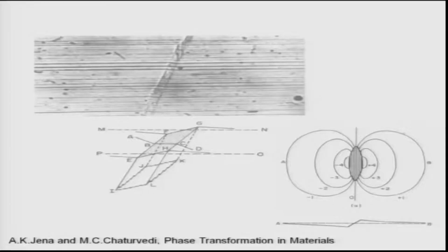You can see there is a distorted region along these lines. Let me just show it. Okay. Anyway, this is the distorted plane, as you see here, along these directions. Now, one can look at the scratch. The scratches were moving on the plane of the parent phase austenite, then they get bent on the martensitic plates, and subsequently they again remain flat on the surface.